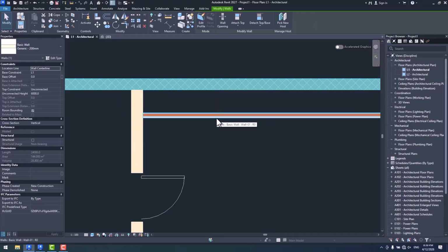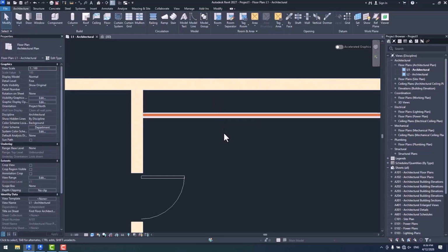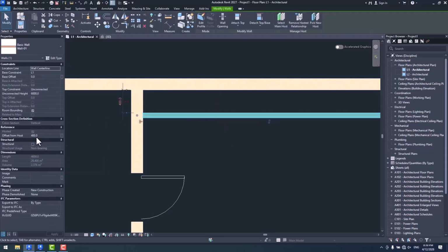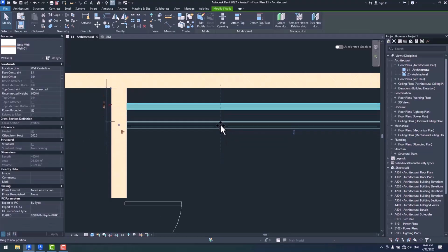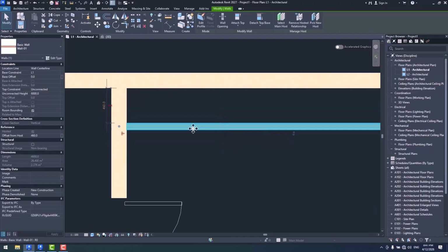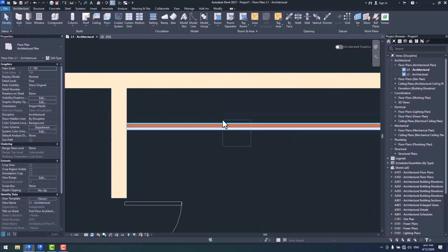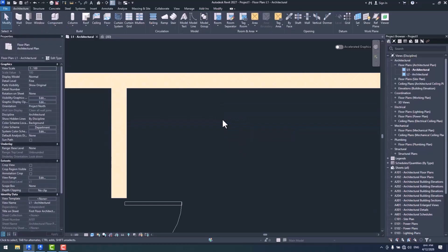Now, as another question, can we control this offset, guys? I mean, manually? Well, yes, we can. So basically, there are two ways for controlling the distance in between these two walls. One would be manually, directly from the viewport, or we can just use this offset option in the properties. Now let's say we want to specify the exact distance or the offset in between the walls before we begin setting them. Well, that's easy as well.